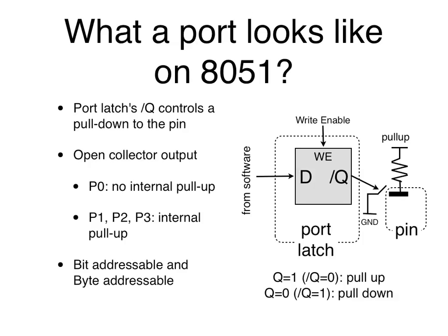You give it an input called D. It could be a 0, could be a 1. And then on the output, it's called Q. It's what you remembered last time. Well, what's the last time? Well, it's the last time you asserted what's called write enable. If you assert write enable and then remove write enable, it remembers that bit. Okay? And so your D input can change all it wants, but the Q part will stay the old value from the last time you asserted the write enable.